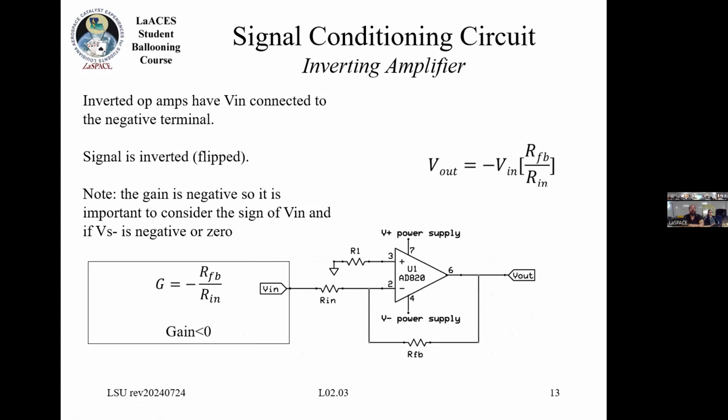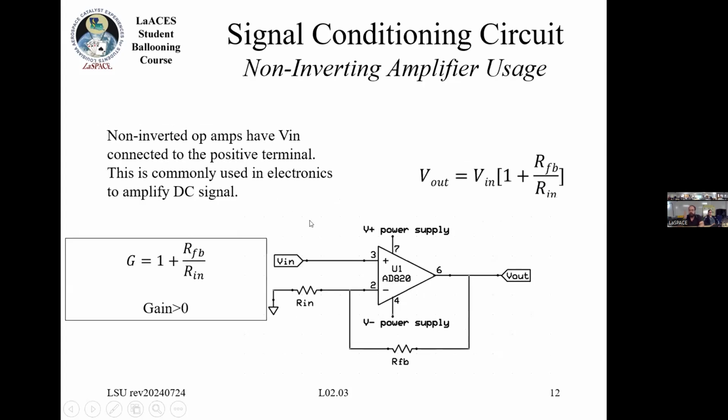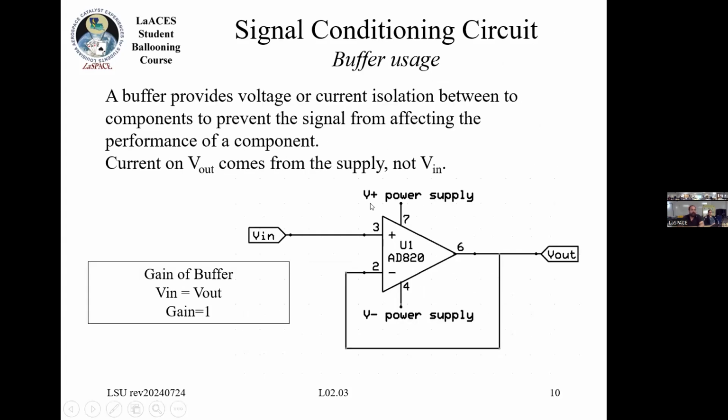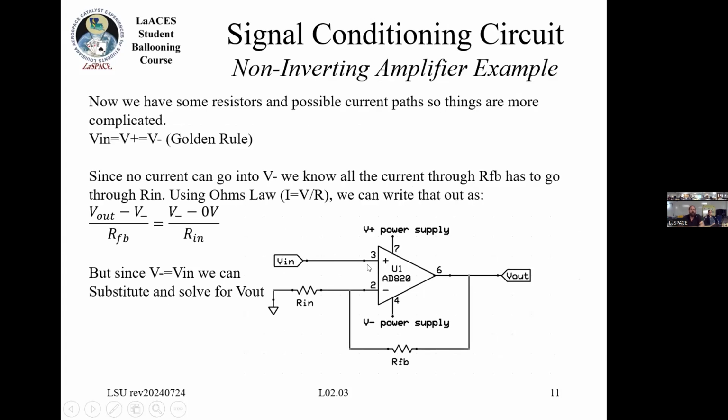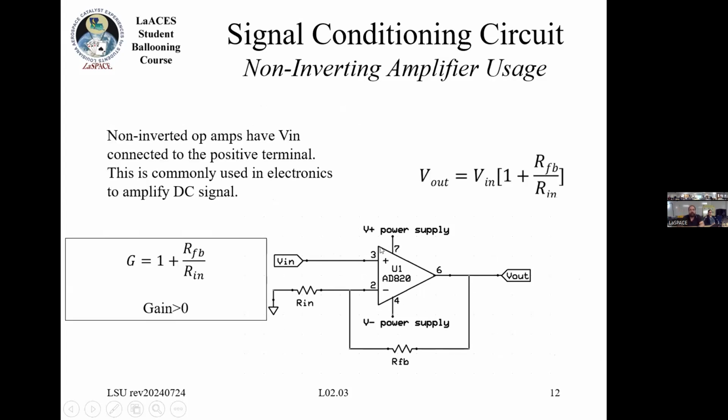And you can build all kinds of different circuits, and they are all going to have slightly different transfer equations. But usually you're just going to look up: I need one of these standard amplifying circuits. How do I build one of these? And what is the equation for that? So the basic ones are the buffer, where it's just a gain of 1. The non-inverting amplifier, where you have a gain of between 1 and greater than, like, 1,000.